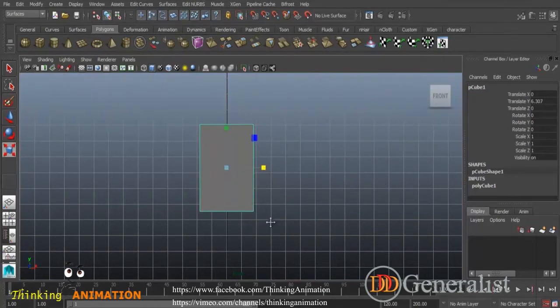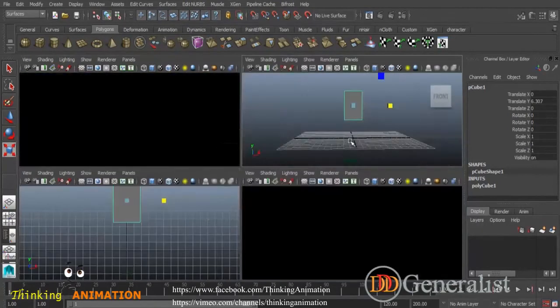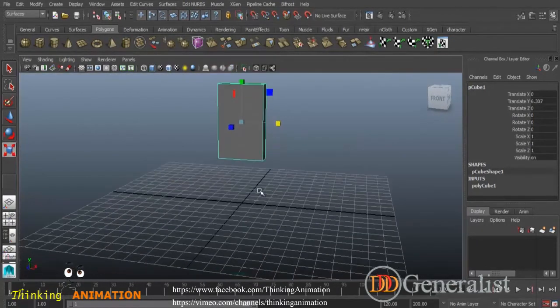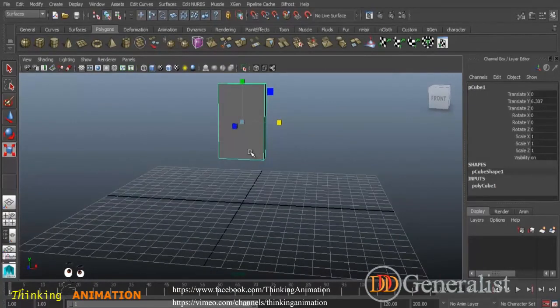And if you want to snap him back onto this grid, meaning at the origin of the grid, and if I want to just snap this pivot point to this edge, how can we do this? I have to select the move tool first and then press the D key and snap to line. If I move it down, it's not snapping to anything, but how can it snap to a line is if you select this option, and hold the D key from the keyboard. This way you can snap it to the line.